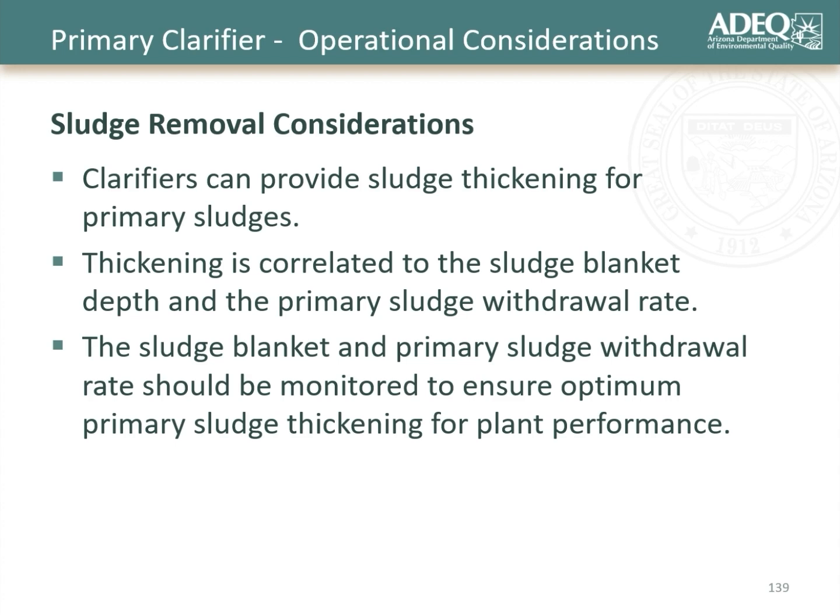The thickening is correlated with the sludge blanket depth, which is related to the primary sludge withdrawal rate. If you remove the sludge quicker, that sludge blanket depth will become smaller, and so you won't get as much thickening. So there's a balance between an optimal sludge blanket depth to make certain that you thicken well enough, but also that the sludge blanket does not get too high, so you have potential washout to consider.